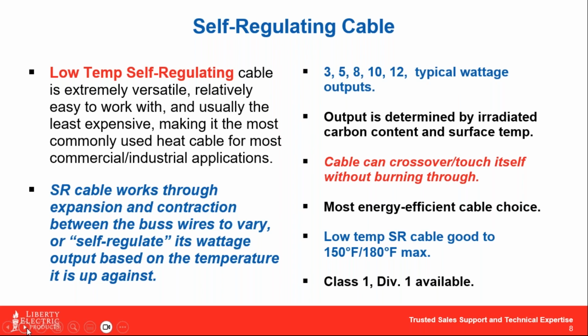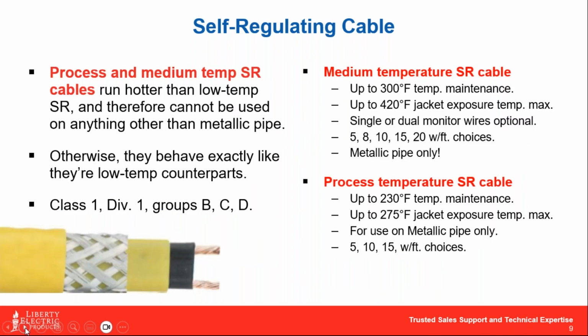And of course, lastly, this is a cable that is rated for class 1, Div 1, Div 2 applications as well. It's a fully sealed unit. So again, the terminations and the fittings that we would put with it would make this compliant with any class 1, Div 1, Div 2 applications.